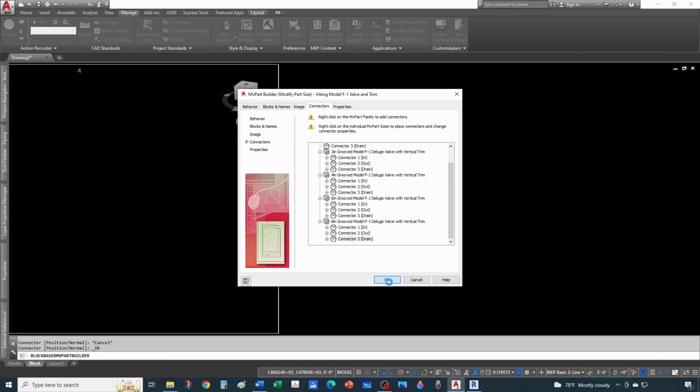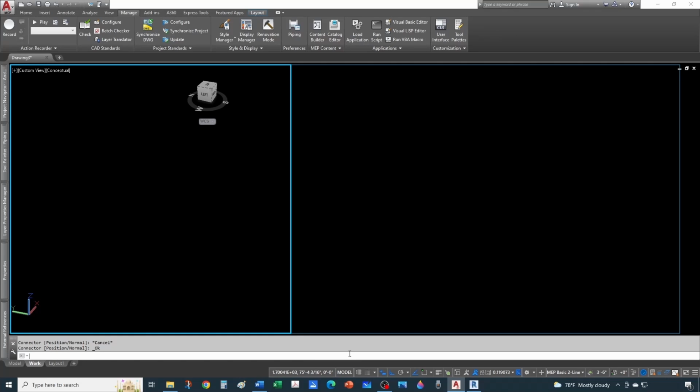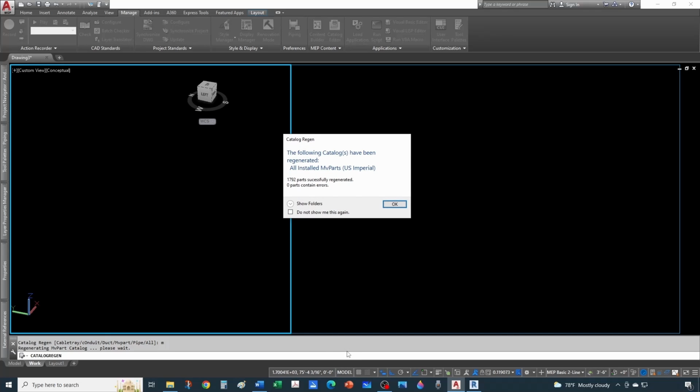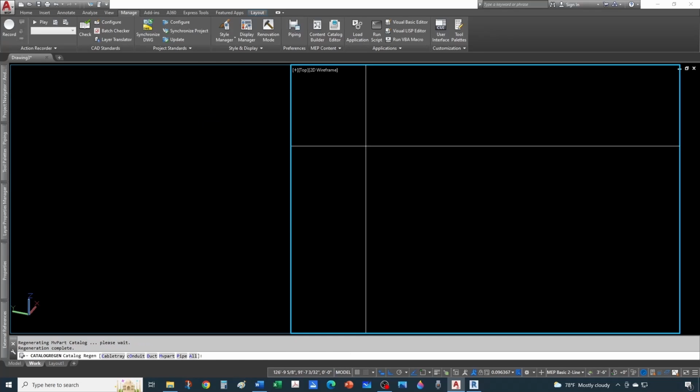Okay, and we need to regenerate our catalog, and for that again you type catalog regen and then M, so that it regens only the MV parts and not the entire catalog, with piping, ductwork, everything. That takes a long time. Alright, so let's give it another shot.